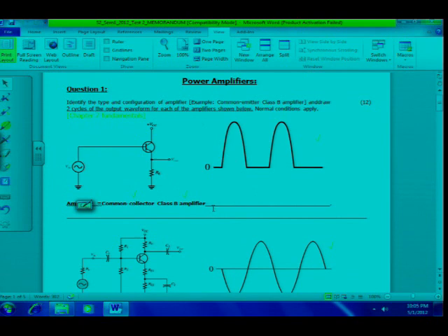first amplifier that we can see there is a common collector. If you can still recall, how do I recognize? I go and look where's the input signal applied, where's the output signal taken from. So the remaining terminal is the common terminal for both AC and DC signals. In this case, it's the collector, so it's a common collector. You get 1 mark for that, and of course it's a class B amplifier because no biasing has been applied to this amplifier. So for the sinusoidal signal that's shown, that is what I will see on the output waveform, only the positive alternations for the 3rd mark.